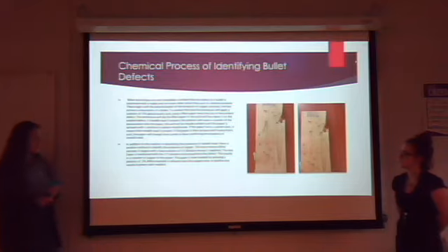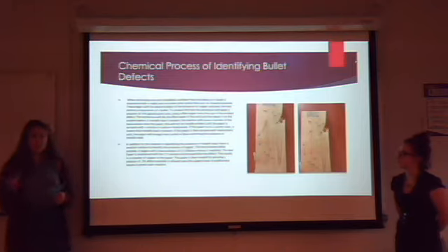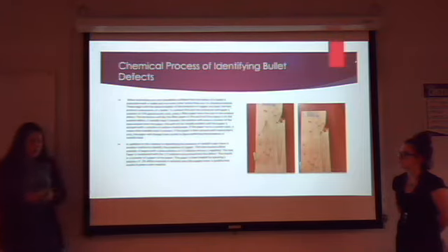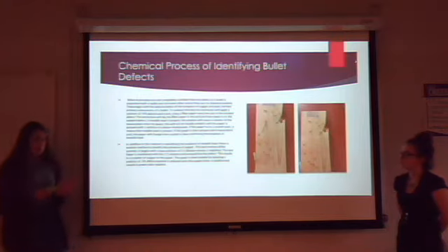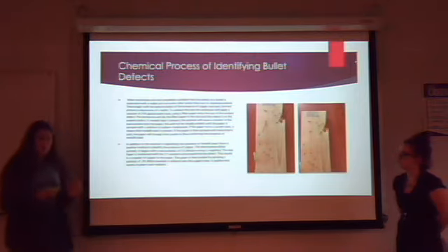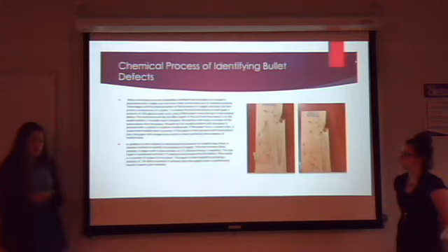This test itself has a second backup, just to double check. If you spray it with hydrochloric acid, the paper will then turn blue, confirming that metallic lead is present. The second one here discusses the presence of copper. You would use a 2 to 5 dilution of nitroso to 1 to naphthol. You put it on a piece of paper that's twice the size of the defect, place it on the defect, and then use a 0.2% dithiooxamide in ethanol, and this would turn the paper green if copper is present.